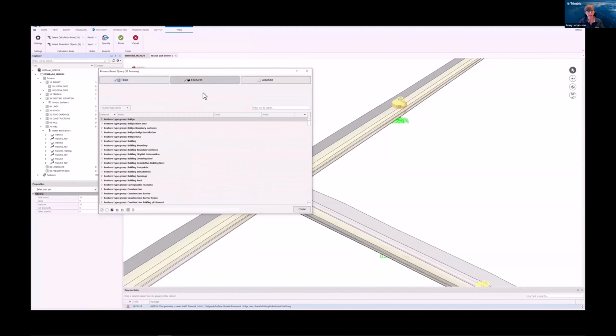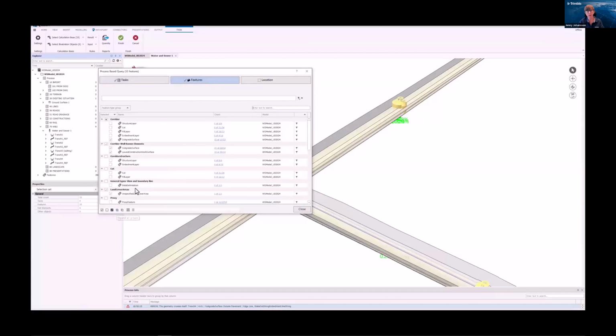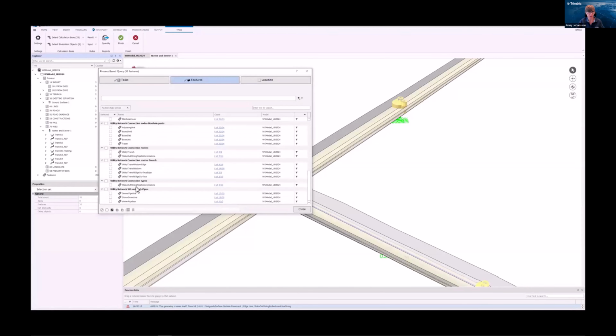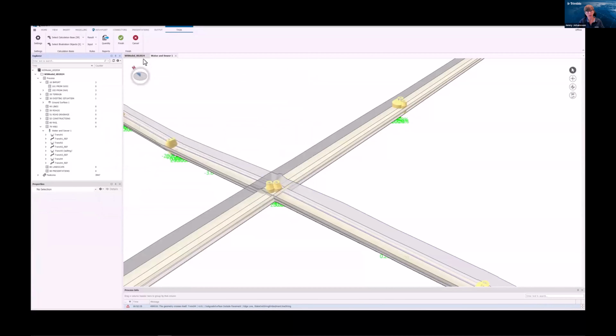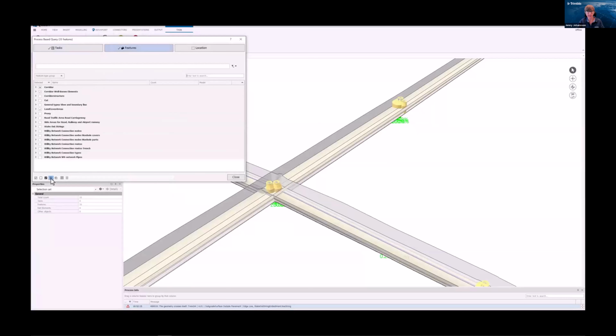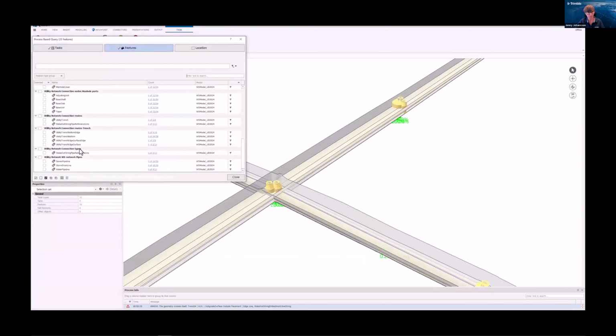And then since we have a selection on the feature level, we go down there and select the outer walls for the trench and the bottom of the trench by selecting utility trench bottom and utility trench edge surface. From here, we finish up, and then we make the same selection for the other trench. Going down to feature level and selecting the walls and the bottom of the trench. And here is to refine our selection actually.